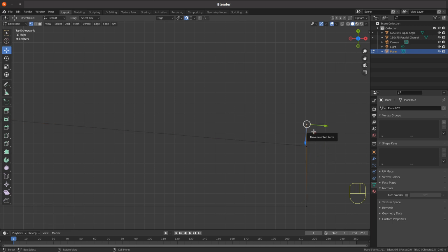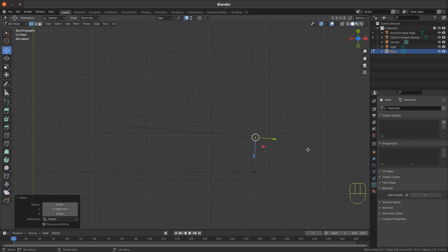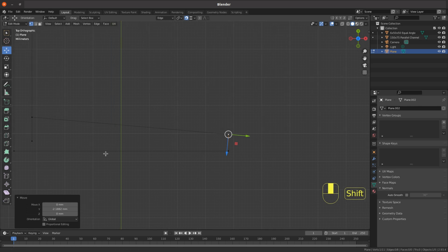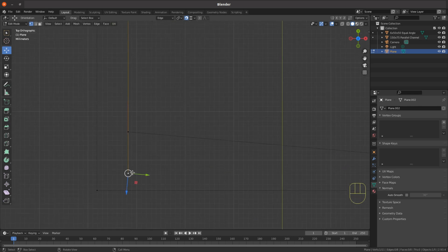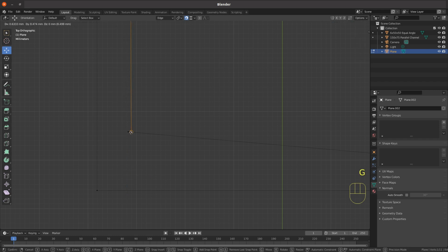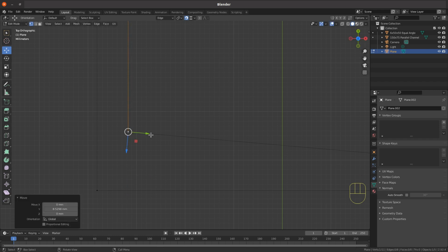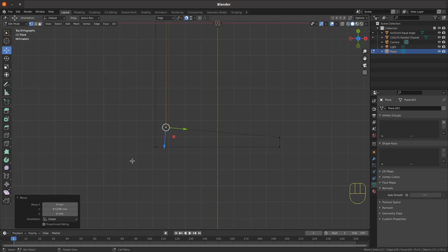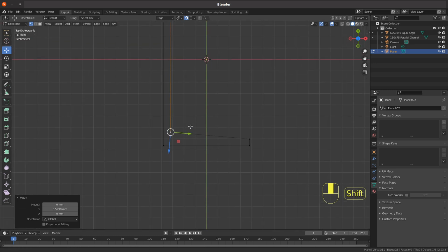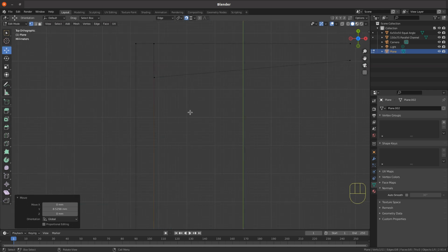So now we can just snap the end vertex that fills between the two and grab it and snap it onto the end of the angled edge, and that puts it in the right place. And do the same the other end, snap the vertex at the bottom of the edge that we're using for the inside of the web, and just grab it and snap it onto the end of the 5-degree tapered edge, and that puts that in the correct position. So we could do the same on this edge now.